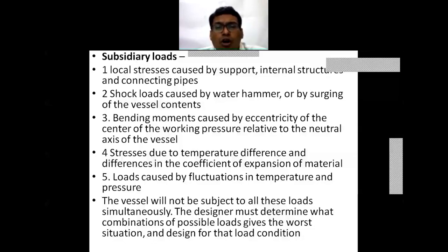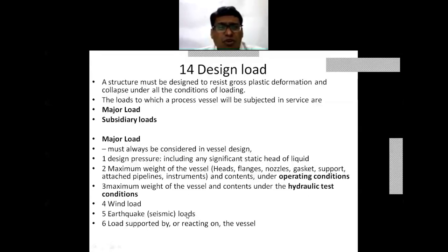Then the loads caused by fluctuations in temperature and pressure. The vessel will not be subjected to all these loads simultaneously. This is an important thing. These major loads as well as these subsidiary loads will not be applied at all times. The wind load or seismic load is a very rare case. It is not there always. Wind load again depends on the geographical condition.